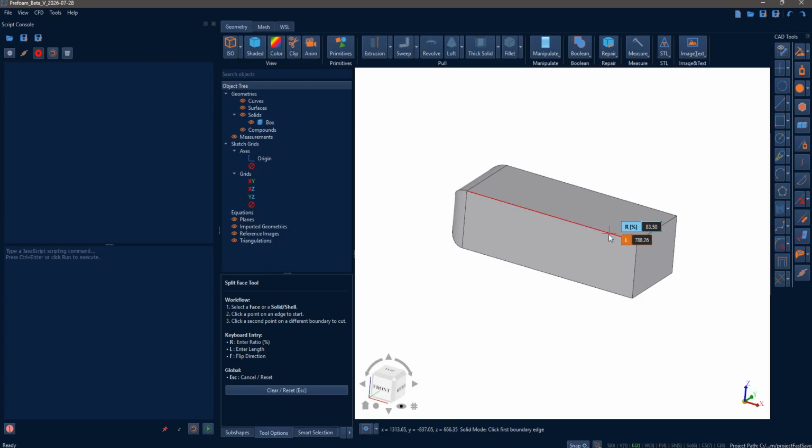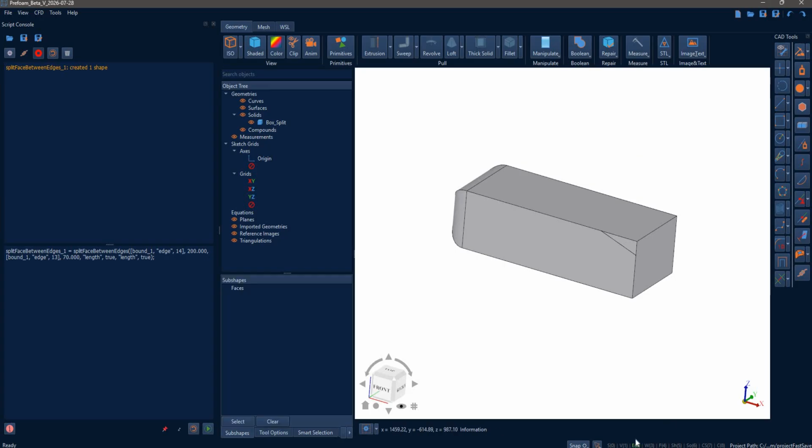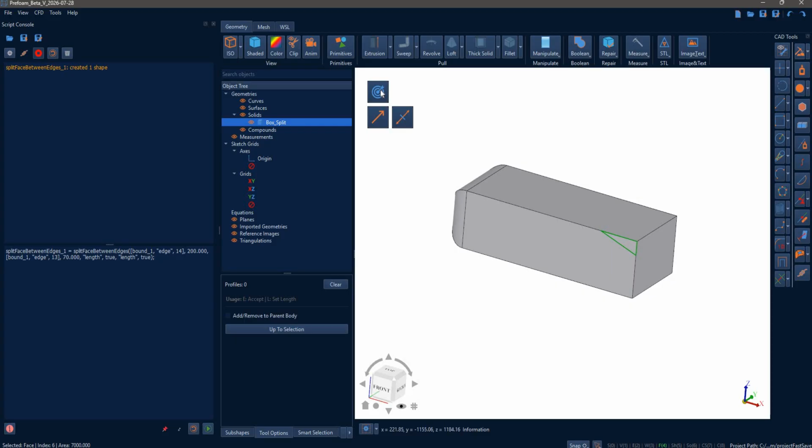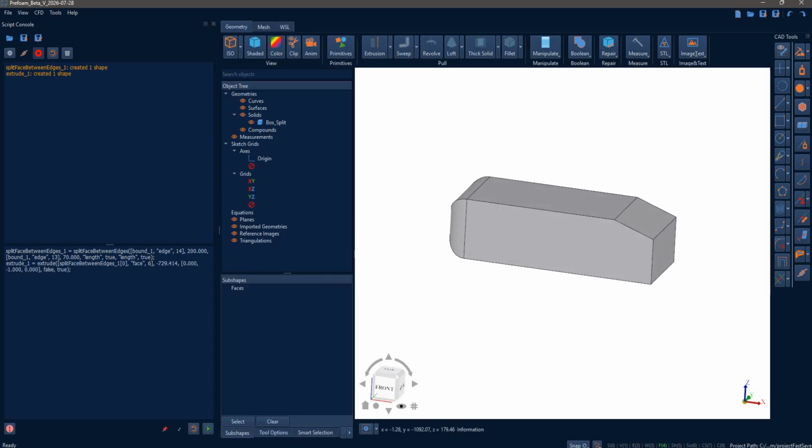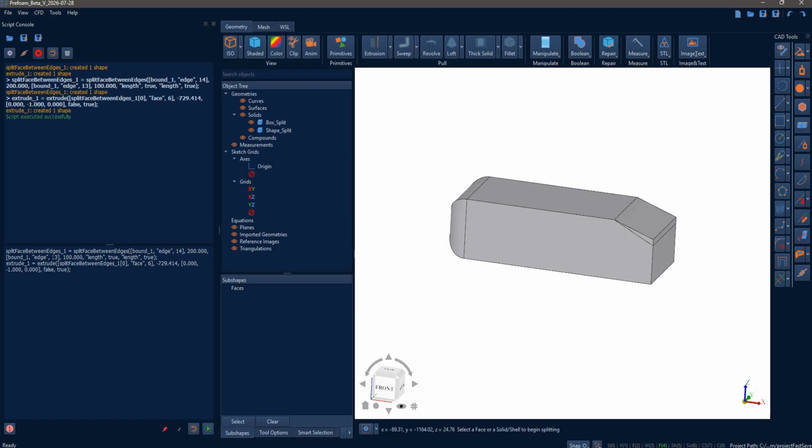It is from the other, so I need to flip, and then length 200, and then from here it is now correctly referencing from the top like this, 70, and then hit escape, remove, hit OK. So you can go now to this section and then replay from that on.